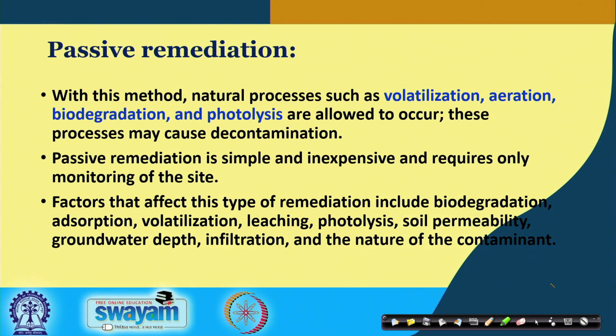Now, in case of passive remediation, different natural processes such as volatilization, aeration, biodegradation and photolysis are allowed to occur. As you can see in the slides, these are the important processes in passive remediation. However, we allow these processes to operate under the passive remediation technique, and they may cause decontamination. Now, passive remediation is simple and inexpensive and requires only monitoring of the site.